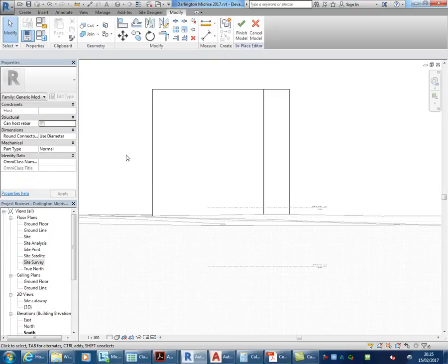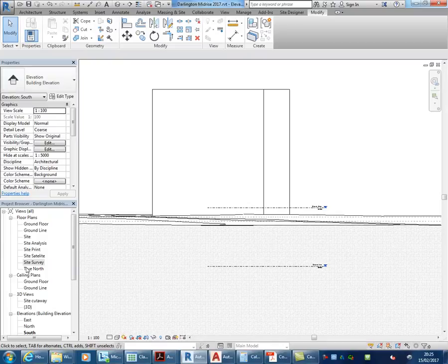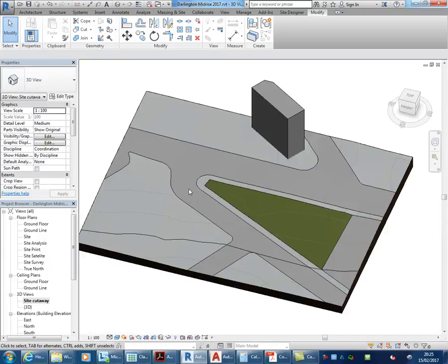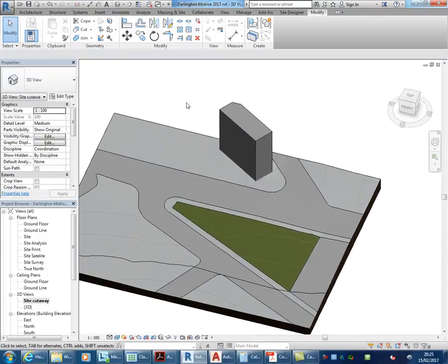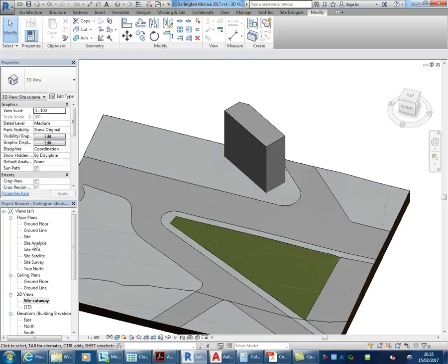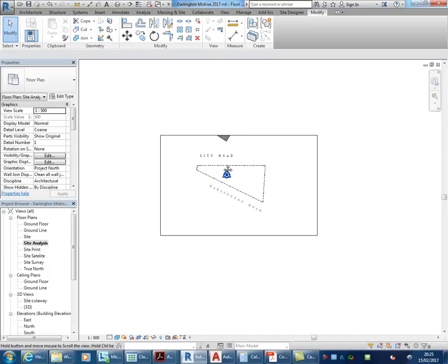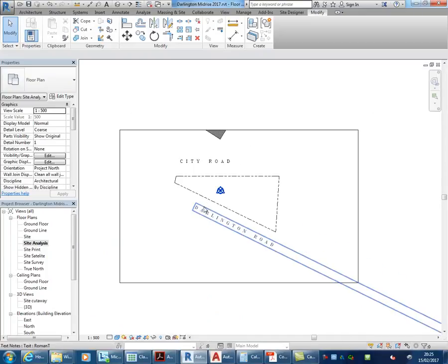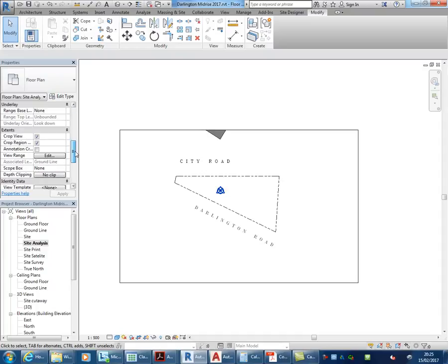Yeah. So those things can trip people up with Revit, but once you've done a few like this, it should work pretty smoothly. And so now I can just keep using the same process. Now you can see here, it's happened. Okay, because I've lifted that level up, it's changed the display, because my view range is taken from that ground line.